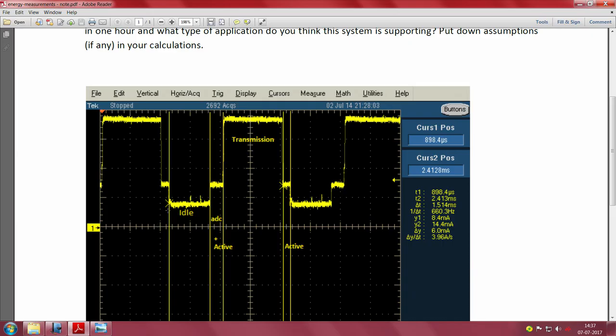Of course, you can do a lot of tweaks in the software code, but you can quickly also say what kind of program has been written, and you can check your software code for its correct functioning by just looking at the current waveform. So you have transmission, then perhaps reception, and maybe even a pairing mode. It is possible that it is also doing a pairing mode. It is hard to say what exactly this part is.